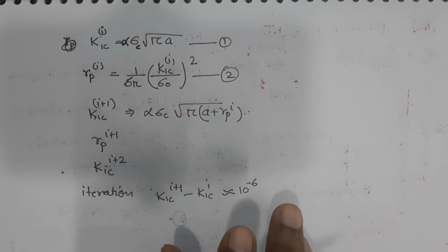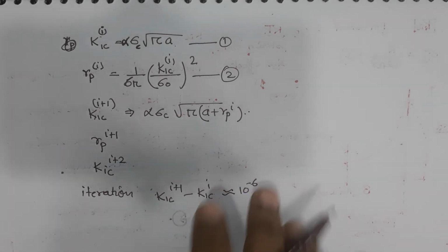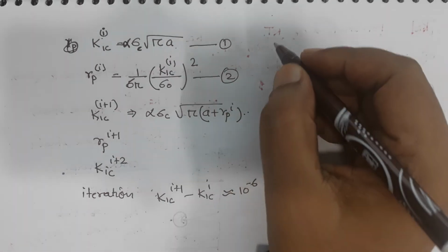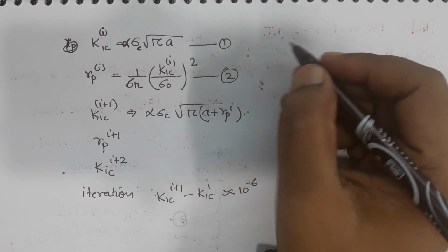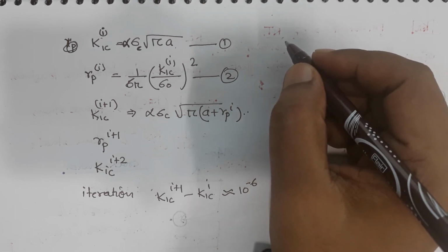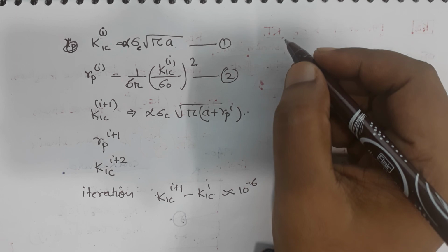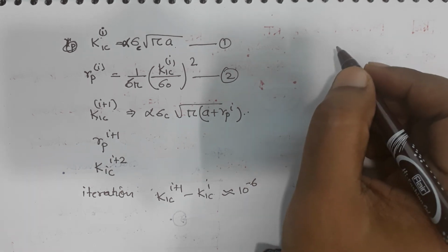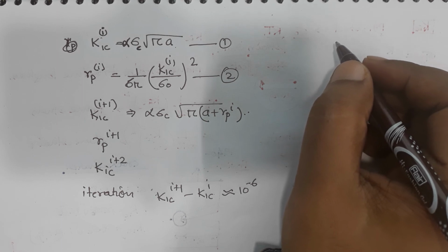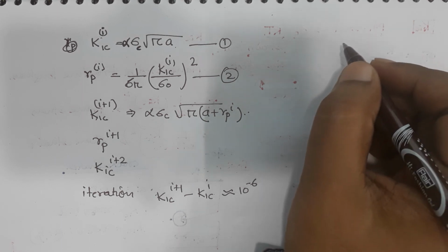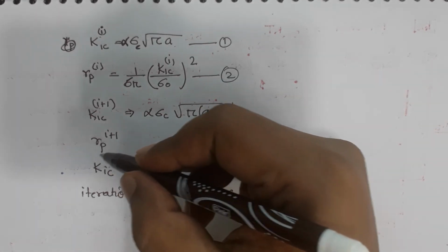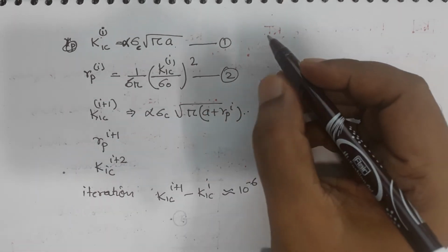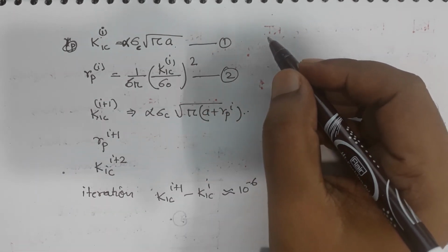Okay. So, this was proposed by Irwin to accommodate some amount of ductility, because we cannot avoid ductility. We can have a material which is completely brittle, but we do not want to use those kinds of materials. We want to have some amount of toughness in our material, and for that our calculation cannot be based completely on the theory of elasticity.